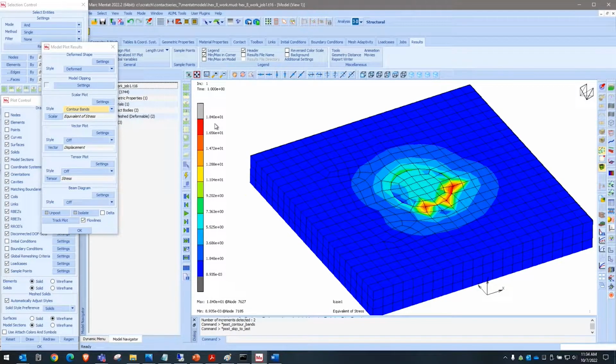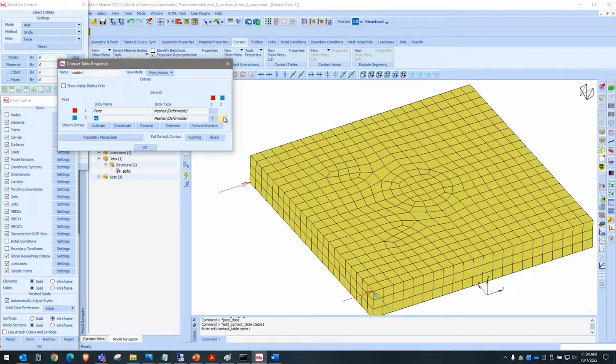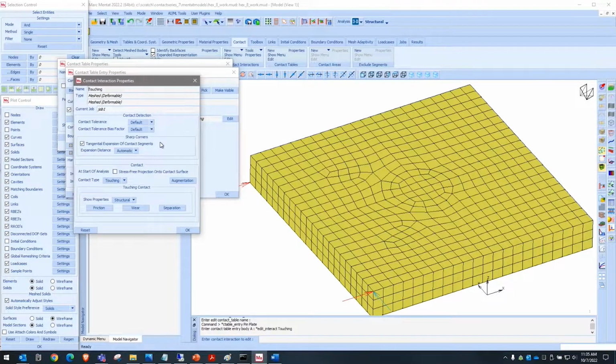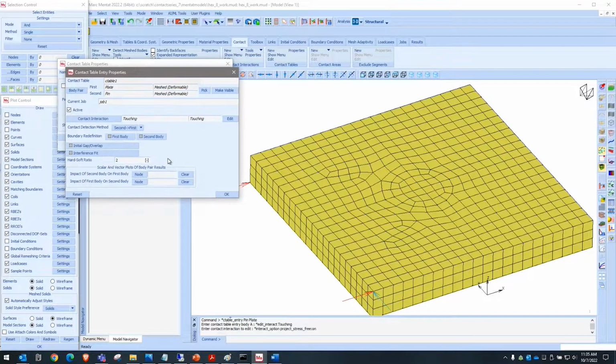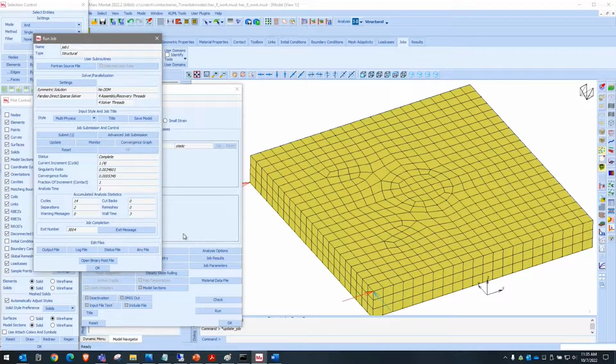Look at the result. And it's now 18 MPa. I think it was 16 before. Okay, so let's start with a cleanup first. Let's try to project stress-free. I just want to see what the effect would be in terms of the initial stress state. So I just activated stress-free. I run the analysis again.